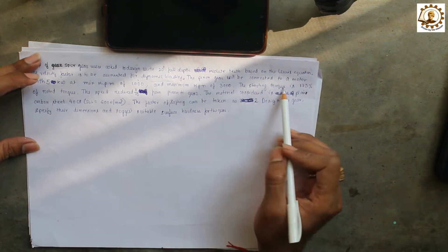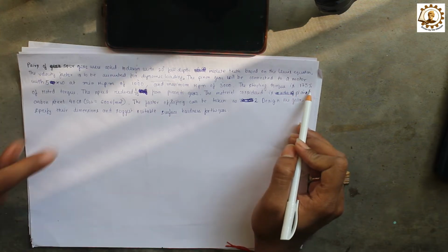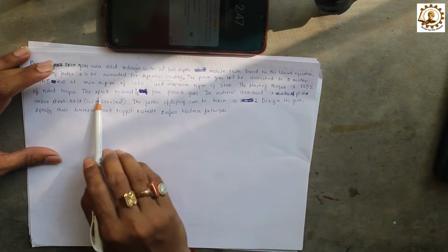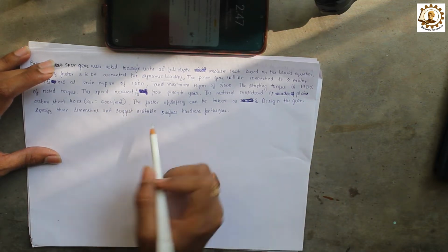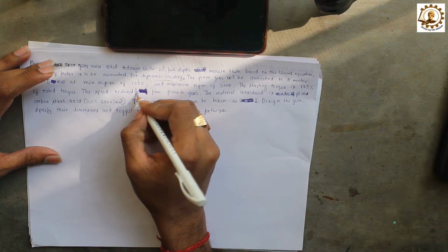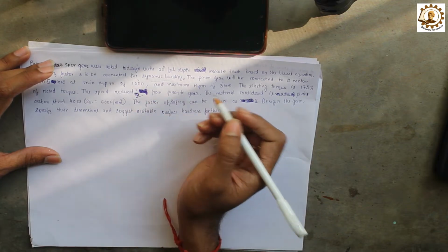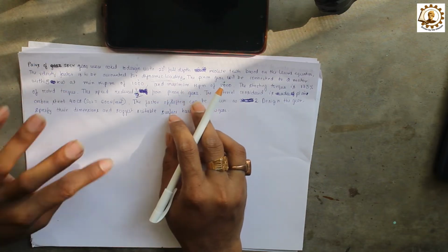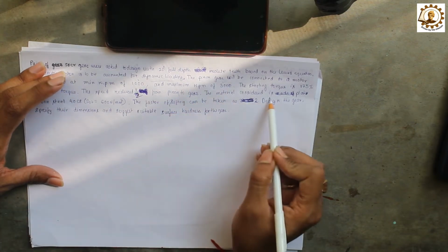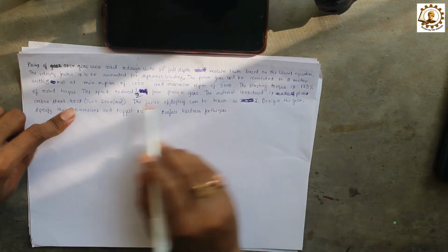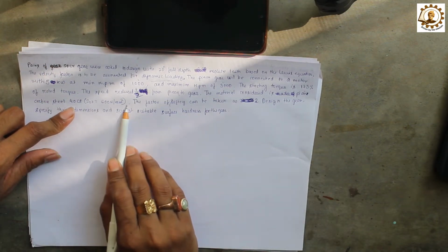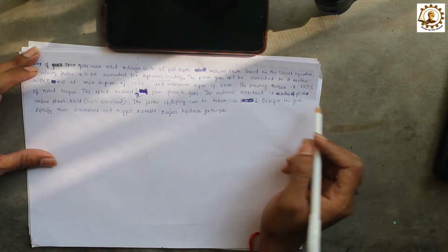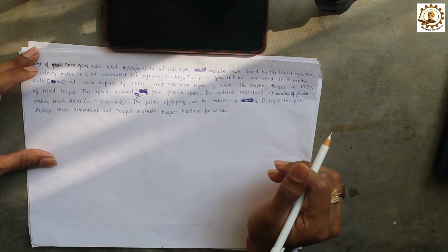The starting torque is 175% of the rated torque, that is 175 into RT. We'll learn about it. The speed is reduced by 1 by 2, that is, from pinion to gear the speed gets reduced by half. The material considered is plain carbon steel, having SUT 600 Newton per millimeter square. The factor of safety is taken as 2. Let us design and see whether the gear is safe or not.